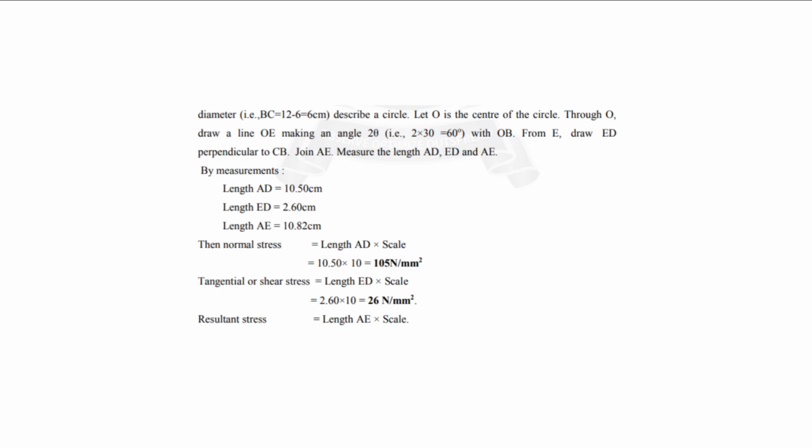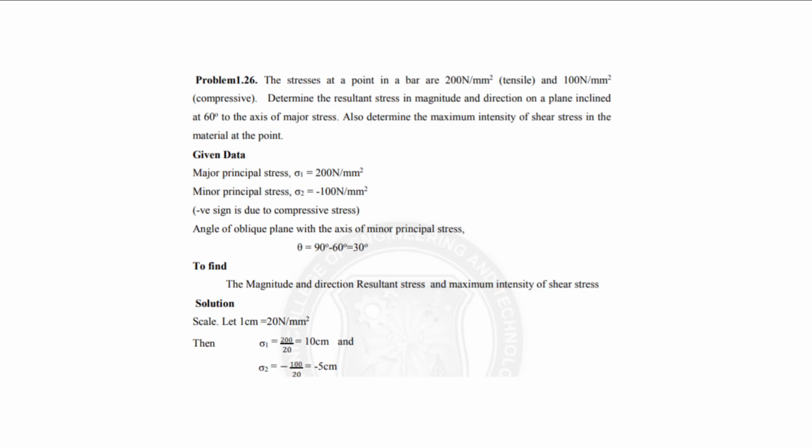Tangential or shear stress is equal to length ED into scale, 2.60 into 10, which is 26 Newton per mm square. Resultant stress is equal to length AE into scale.